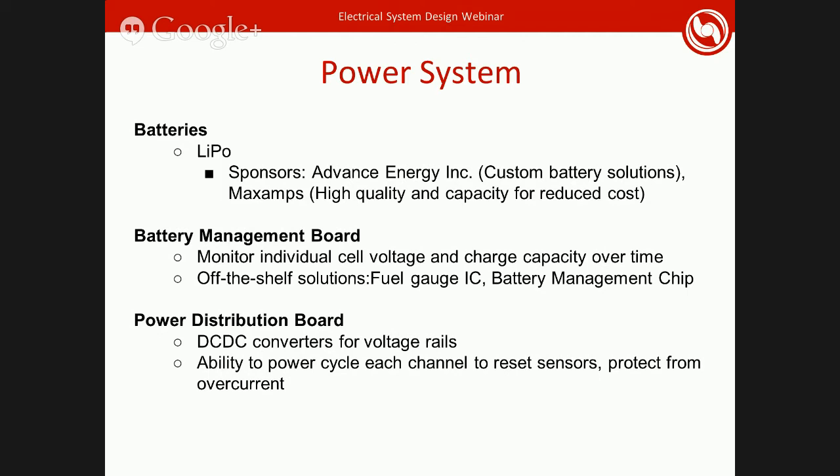The nice thing about using DC-DCs is you come out with a more stable output, whereas the battery output voltage will change anywhere from 22.8-ish to 25.2. Some sensors will require a more fixed range of voltages. For example, the computer we were using last year could only handle plus or minus 0.6 volts of ripple noise on our 12 volt output. So had we directly connected this to a 12 volt battery, our computer would fluctuate between being on and off. So DC-DCs are quite stable.